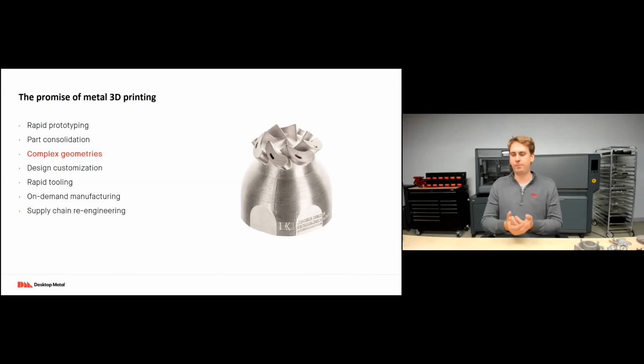But if I remove material from a part that we're going to print, now there's less material that needs to be printed. We're removing cost. We're removing print time. So justifiable complex geometries. We're now able to have much, much more complex parts than we could justify if we were using a traditional manufacturing method, because we're printing them in an additive method.